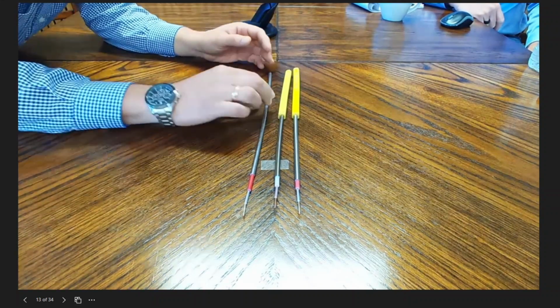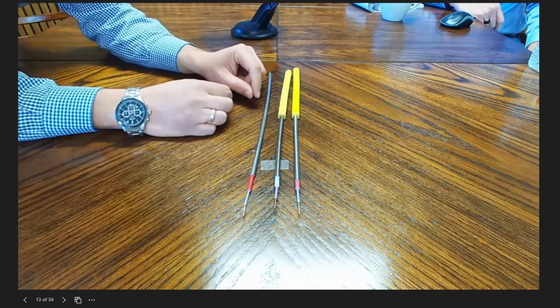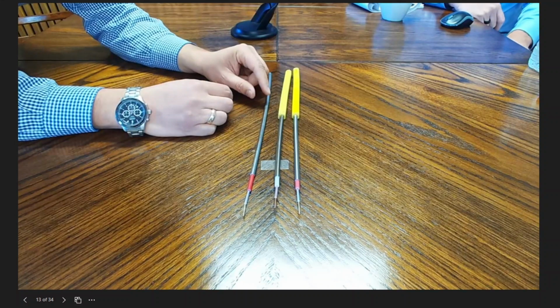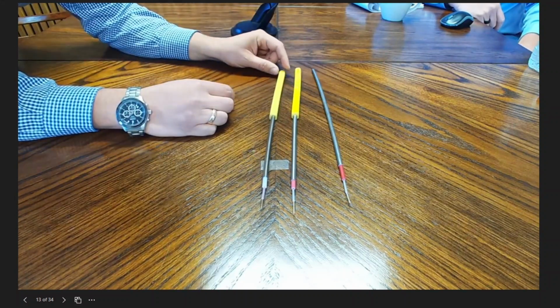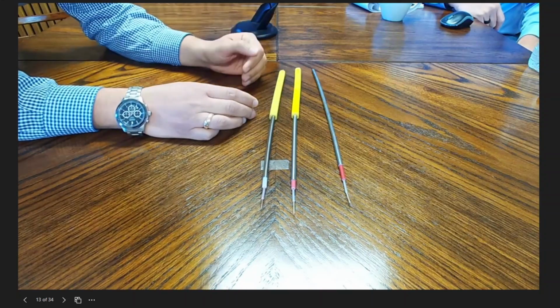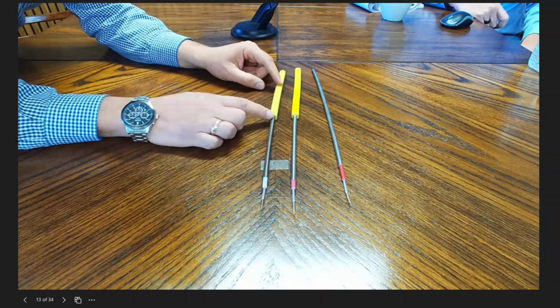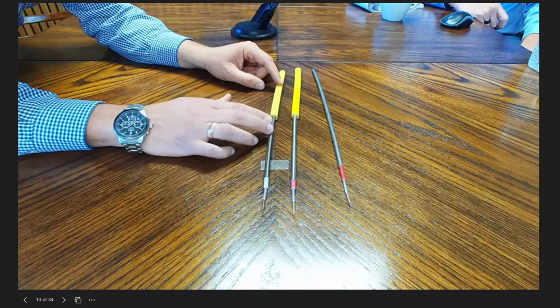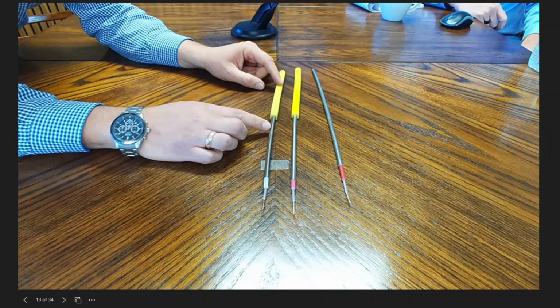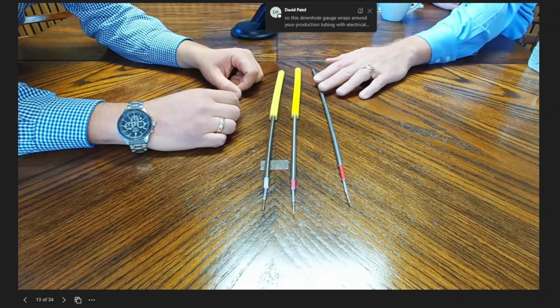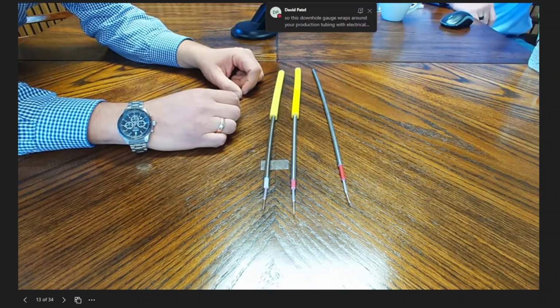Now let's talk about when it's highly deviated. If it's highly deviated, you want an extra layer of protection over this armor. Remember, this quarter-inch armored tubing is what maintains the electrical integrity of the gauge system. What is the OD of this bare TEC cable?